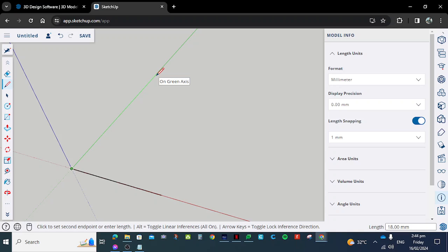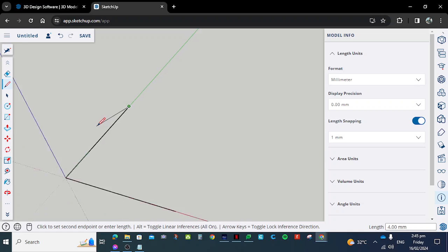So if it's a bit hard for you, you can actually just type the number of the length that you require. Let's say I need 10. So instead of positioning the tool, making sure it's 10 millimeters, you can just ignore it. Just make sure that the line tool is along the y-axis, and then just press the number. So I need 10. I just press 1 and 0, and I'll press enter, and then that's it. So that makes our task a lot easier.